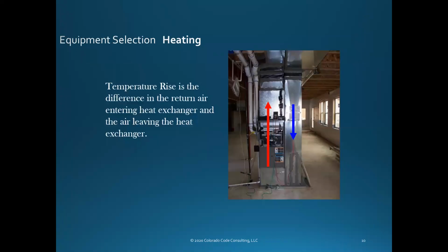All right. Just a really quick snapshot of temperature rise, right? You've got the cool air coming down, sucks up nice, bottom return. Comes up through the heat exchanger, so you're putting a temperature probe up here to see what the temperature is, putting the temperature probe in here, and the difference between the two is my, quote, temperature rise. Again, if temperature rise is correct, the furnace is working correctly. I don't care what the airspeed is. Kind of a clue for next week.